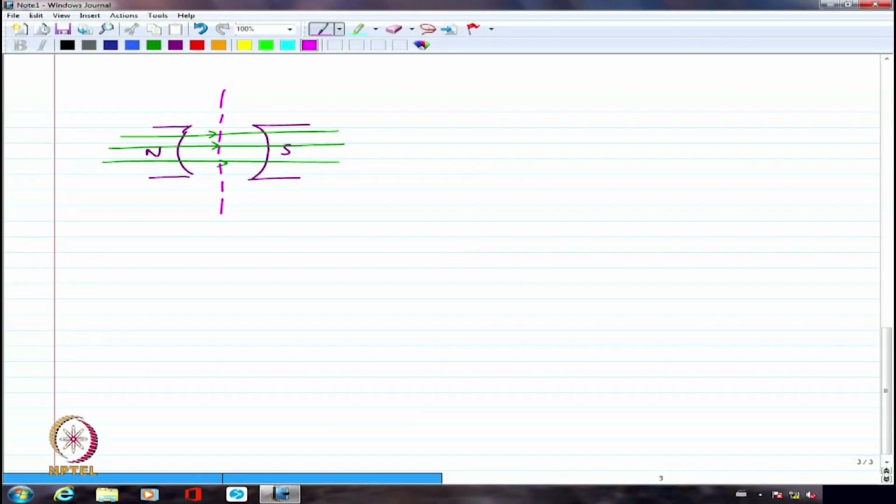That way, the conductors change over from dot to cross current or cross to dot current exactly along the neutral axis, so that it becomes simpler, because the current is going to be really minimal or almost close to zero at that point. Because of this, I am going to have mostly the changeover from plus to minus current or minus to plus current pretty smoothly, because it is drifting from the South Pole's influence to the North Pole influence and the North Pole influence to the South Pole influence.